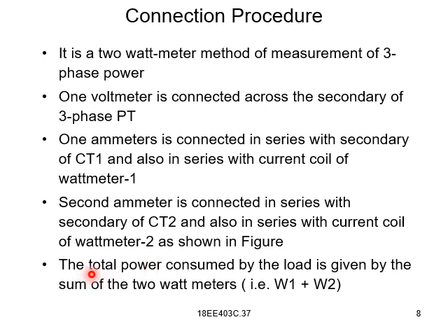And the total power consumed by the load is given by the sum of 2 wattmeters, therefore W1 plus W2. And we'll see the diagram.